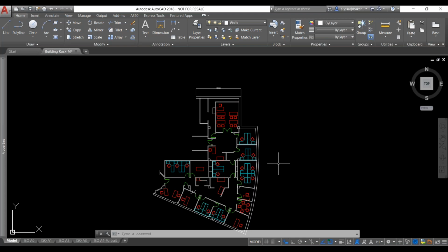What that basically does is, if you want to set a marker to revert back to after drawing a whole bunch of things, you can set an undo mark. To do that, we're going to type in undo. If you press enter, we'll see a whole bunch of settings or options down here, and you want to click on undo mark.